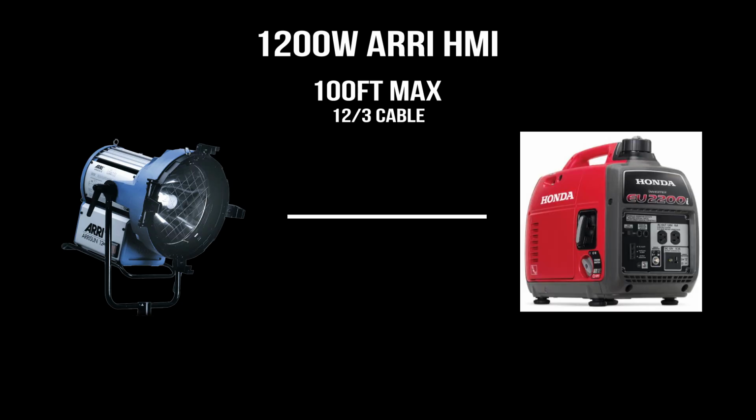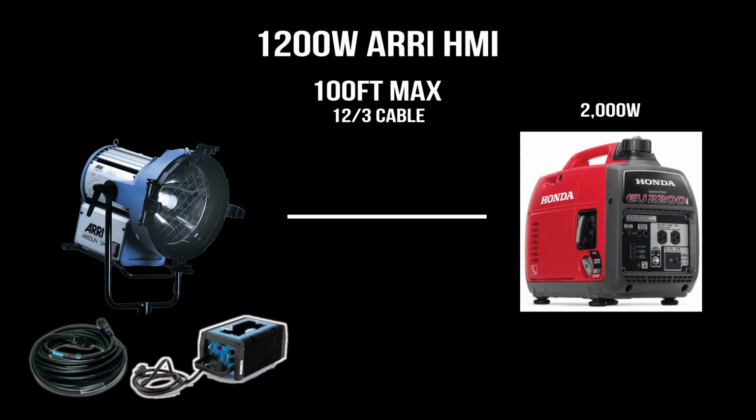So my 1200 HMI light has a limit of 100 feet of cable from light to generator, and that's using 12-3 cable and running it off a 2000 watt Honda generator. Any more cable than that and the light strikes, but it won't hold for more than 10 seconds. And keep in mind, this also includes the 50 foot of head cable from ballast to light and the wattage of the ballast. So it's probably in the range of 1400 watts altogether and using about 150 feet of cable technically. Over 100 feet, we're losing too much voltage to power the ballast and light properly.